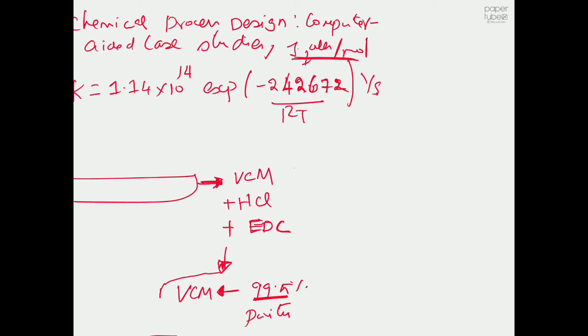Before going into this distillation, one thing we need to remember: the stream that comes out of the pyrolysis chamber will be at a higher temperature, because we are maintaining the pyrolysis chamber at a very high temperature of 550 degrees centigrade. So once the stream comes out of the pyrolysis chamber, we need to quench the temperature of the stream. If not, you will end up with coking, and sometimes your main product will start to degrade with time due to the high temperature.